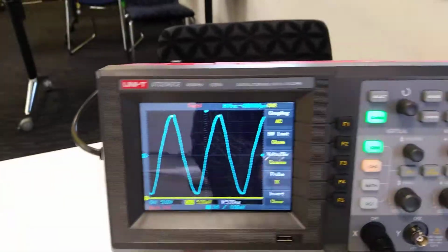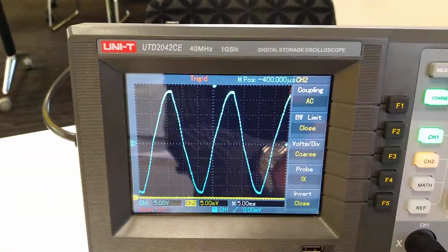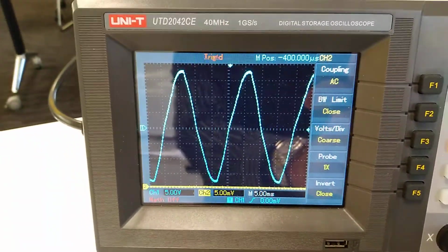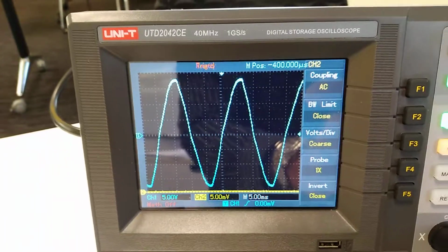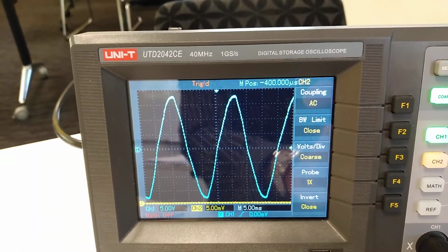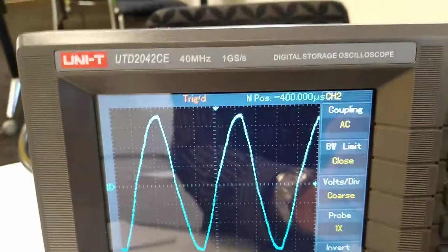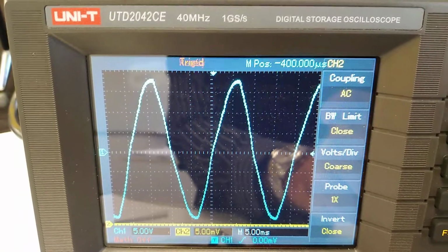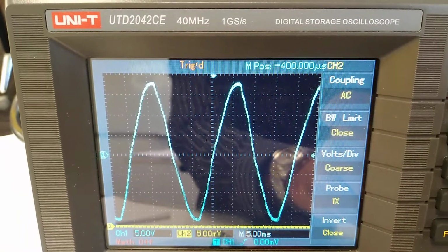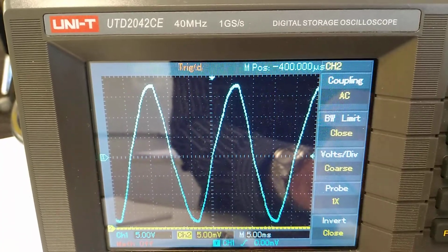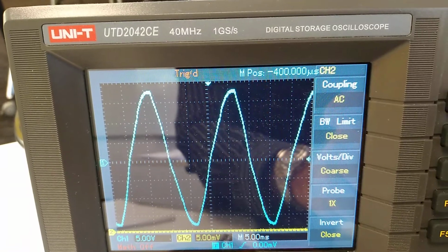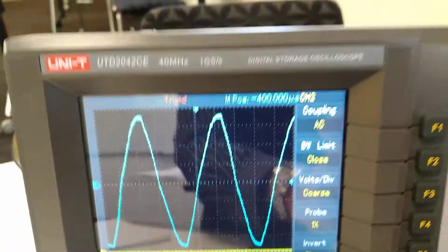So now looking at that value on the oscilloscope, you'll see I'm on channel 1. My voltage range is 5 volts per division, and if you come up there on the positive going peak, you'll see how many divisions have I got? 1, 2, 3, so that's 15 volts, and then it's about 2 volts or so over that, which is about 17 volts as my peak value positive going, and the same will be on my negative going half cycle as well. So we'll just calculate that out.